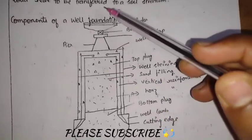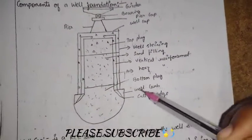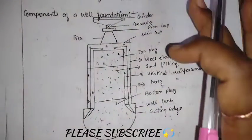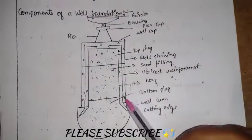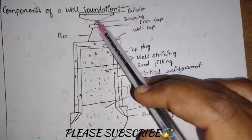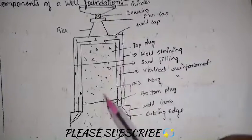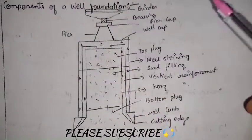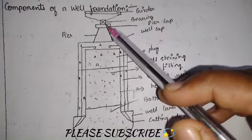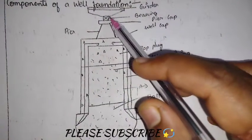Whenever we have to transfer the upcoming load onto the soil stratum below, we have to go for this well foundation. So this is just a diagrammatic representation of the well foundation. Coming to the top one, this is a girder, that is a beam-like structure, and it is having a bearing. To connect this girder to the well foundation, we are having this bearing, and this is a pier, that is a pillar-like structure, which has a top surface on which the bearing is provided.